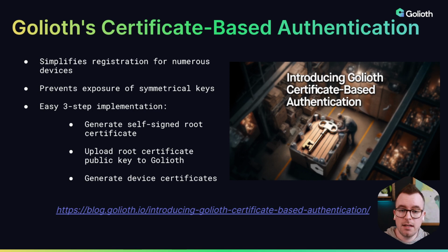It also ensures that compromised devices don't expose their keys. This helps keep things safe. And the process for implementing it on Goliath can be done really in 3 steps. That's generating your self-signed root certificate, uploading that public root certificate, the public key, to Goliath, and then generating device certificates.